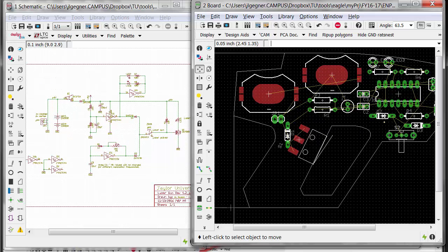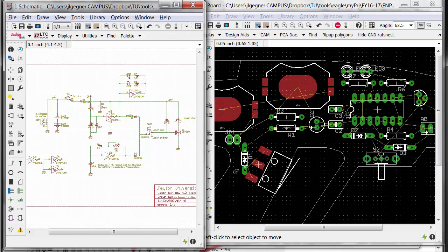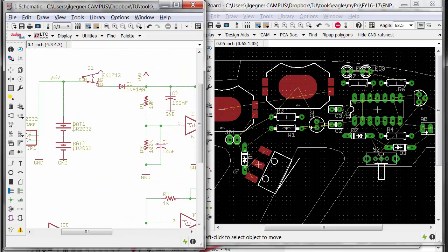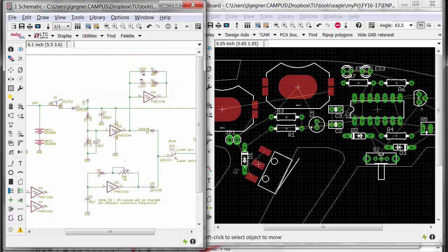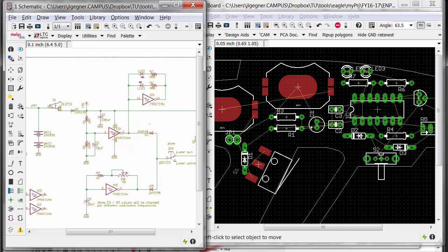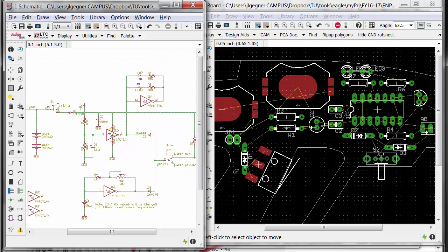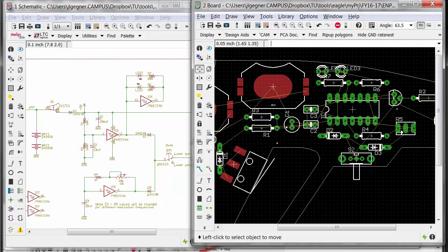Now you might wonder, how do you know how to place parts? Your guide is really your schematic. Sometimes this works really well when you're doing discrete parts. When it doesn't work so well is when you have an integrated circuit that has multiple gates. For instance, in this case, the IC, the Schmitt trigger inverter, where all of these gates are centered around this one IC, so you can't spread these things out very well. So it's kind of just trial and error a lot of times.